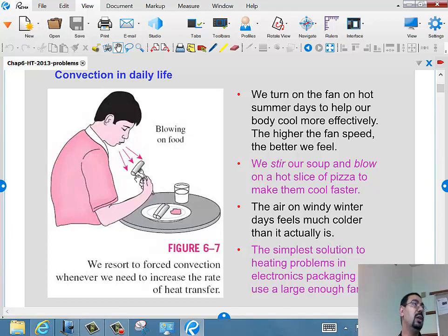So what's the way to improve that conduction? If only the temperature difference were much bigger. If only we could replace that hot layer of air with a fresh cold layer of air, that would probably get even more conduction out of the wall. I keep stressing the fact that the first layer is conducting with the pipe. It's temperature that we are worried about.